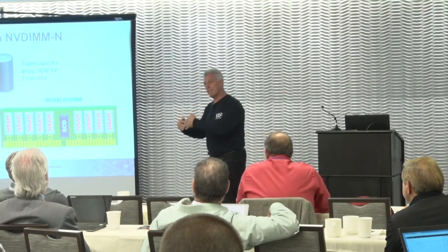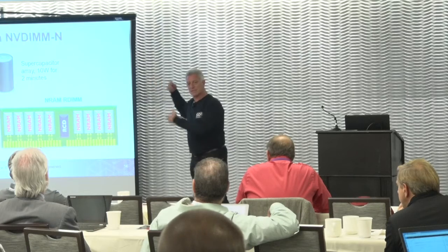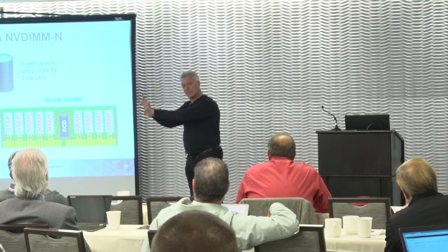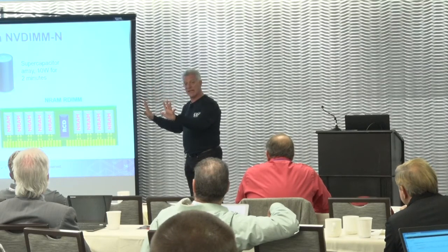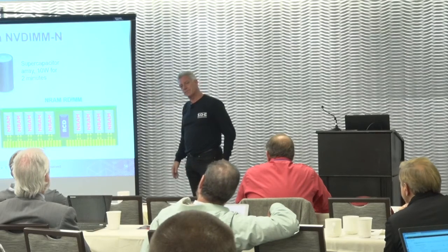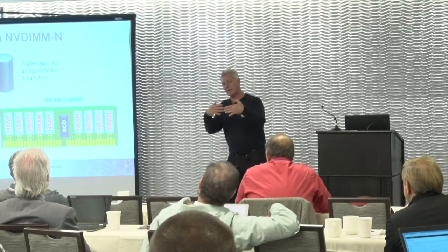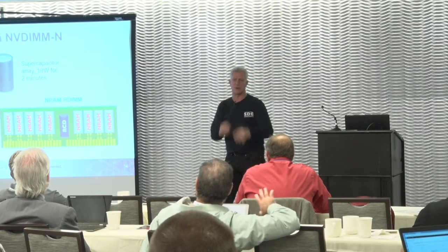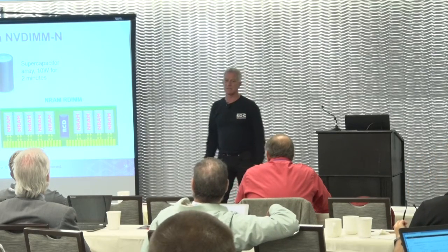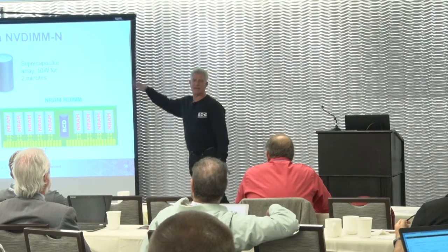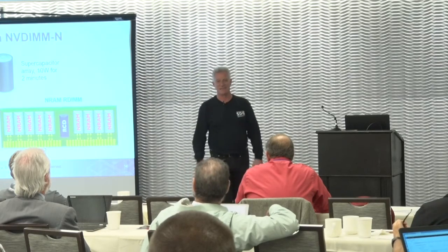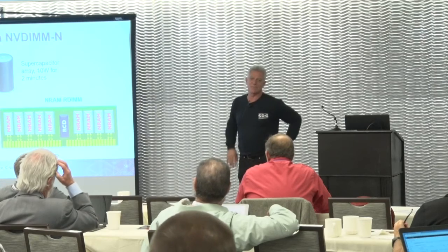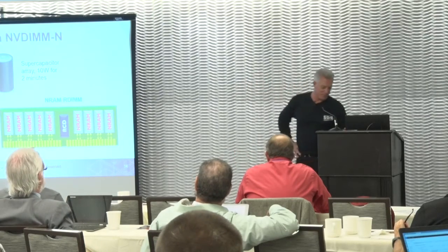With this architecture, the same thing. It completes the burst that's in process and stops using it, and then power can go away and there's no problem. It's only when a data burst gets interrupted that you have data loss. But that's consistent with any persistent memory, right? If the bus is screwed up, your data's screwed up. I can't solve that problem.